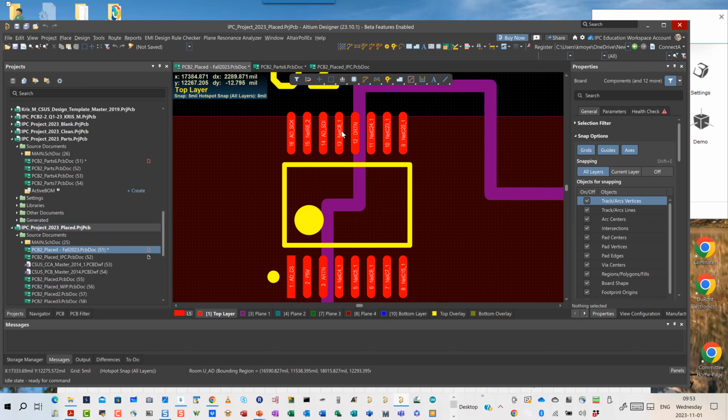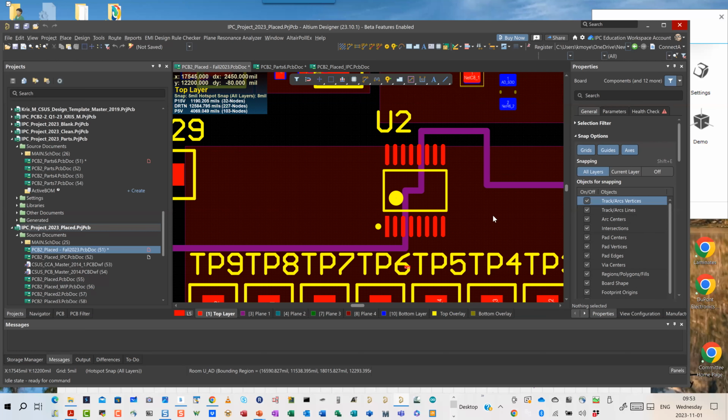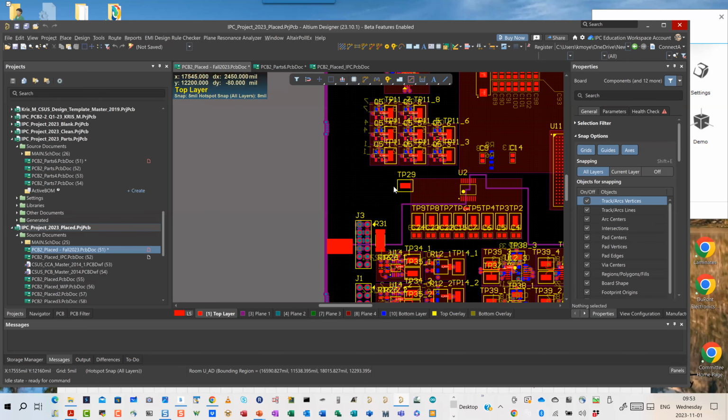There's the digital return there, and these are the programming connections right here: chip select, clock, SDI, SDO, and so on. So yeah, this particular device was not physically laid out very well from an A to D point of view.